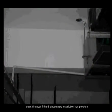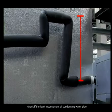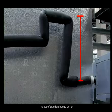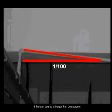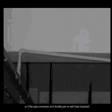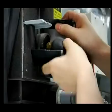Step 3. Inspect if the drainage pipe installation has a problem. Check if the level and consistency of the condensing water pipe are out of the standard range or not. If the draining pipe is jammed, the condensing water cannot be discharged. Check if the lean degree is bigger than 1%, and if the pipe connector and throttle part are well heat insulated.